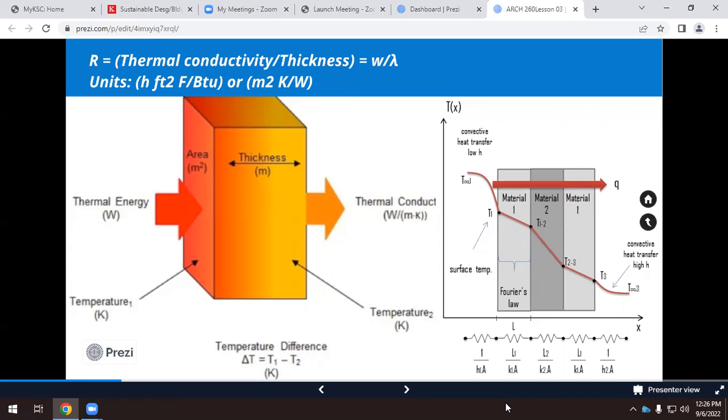So if we have this wall, what's the thickness of this wall? You can see the thickness of the wall. The first layer is brick. Probably we will have like 10 inches of brick, and the rest probably it will be thermal insulation. And then we have a finish. We have this finish. And this is gypsum board or plaster board. So this would be like 1/2 inch. We have 10 inches of brick, and the rest probably it will be thermal insulation like this.